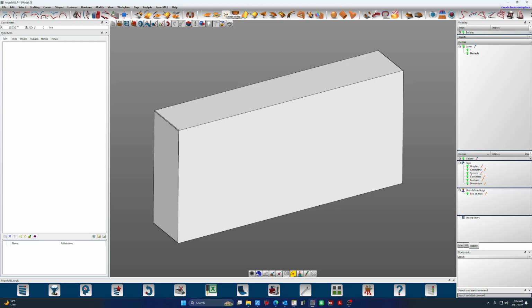Linear sweep. Linear sweep is taking an edge, a curve, some piece of geometry, and sweeping it off into space. We can drive the vector with curves, with points, relative to the world coordinate system, relative to an active work plane. Awesome tool. And swept plane has another cool utility, which is that we can make it completely enclosed and turn it into a solid right at the CAD tool level. I'm sure we'll cover that when we get there.